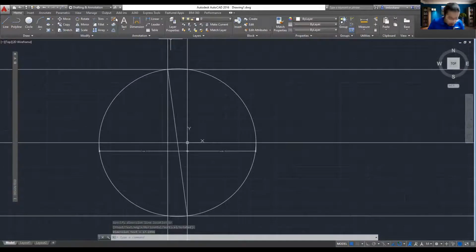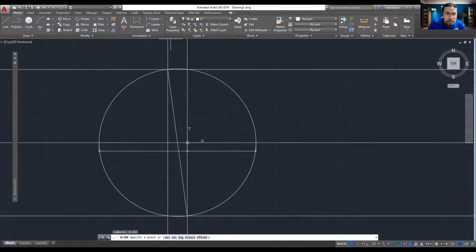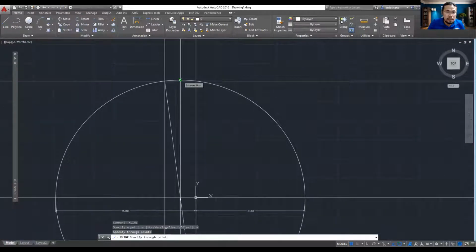And then we create the vertical line. It's going to be vertical, and it has to pass through the axis. And we have now our maximum shear stress identified by the coordinate of the maximum shear stress and the average of the principal stresses.